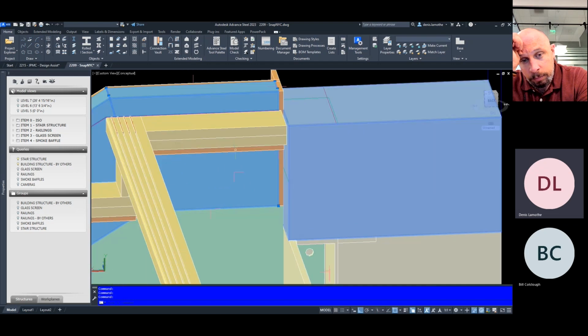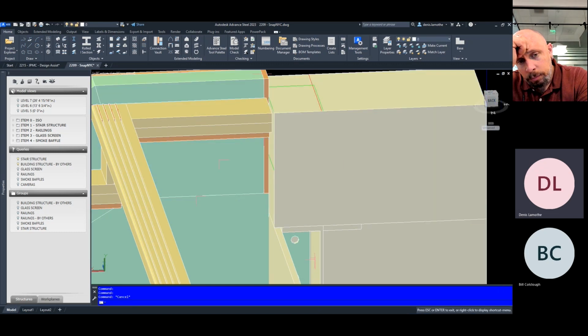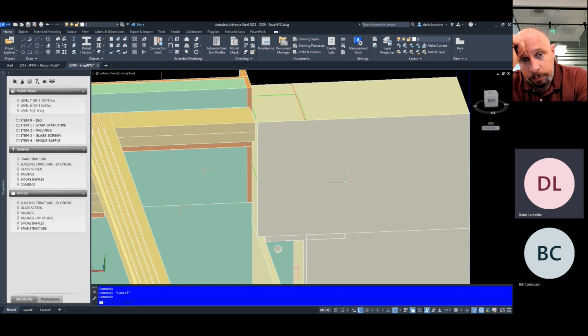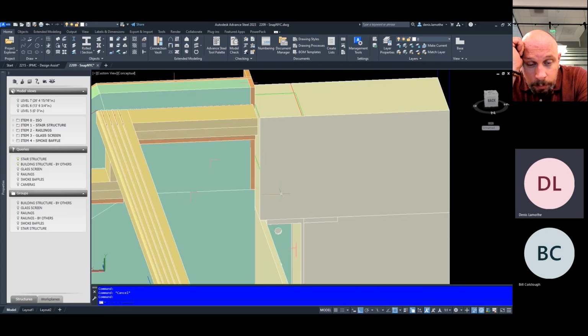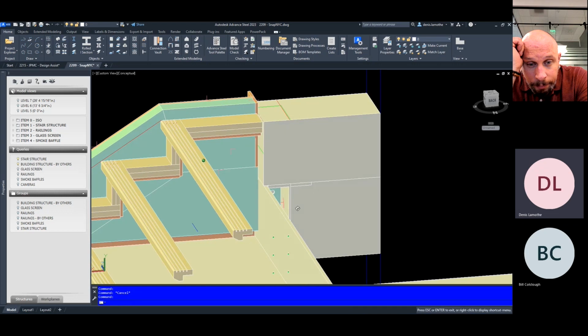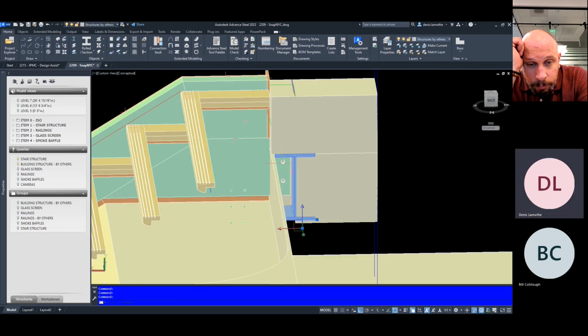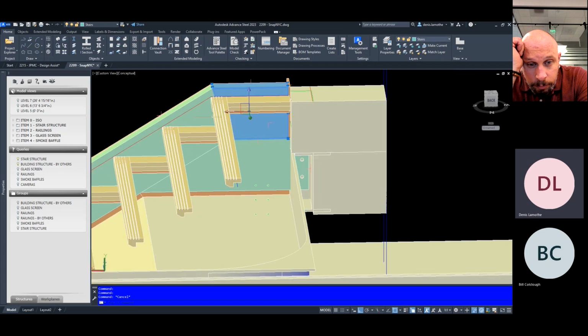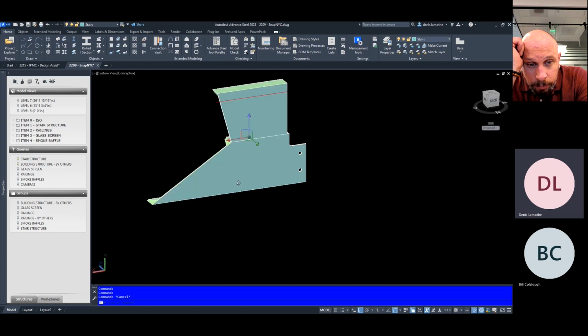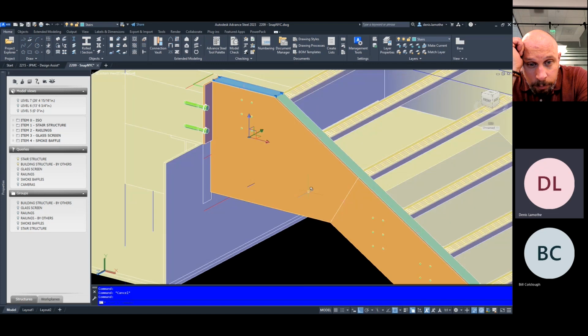We have to consider that there's a tread plate here, and so our height was a lot less than what we would have needed. Plus, there could be issues with rebar, or if it's post-tension concrete, they really don't want us drilling and cutting and messing around with those, and that can have an impact on our ability to anchor to the concrete. So for this particular example, we were able to tie into an I-beam below. And to do so, we had to build out our stringer so that we had a separate section of channel for this example.